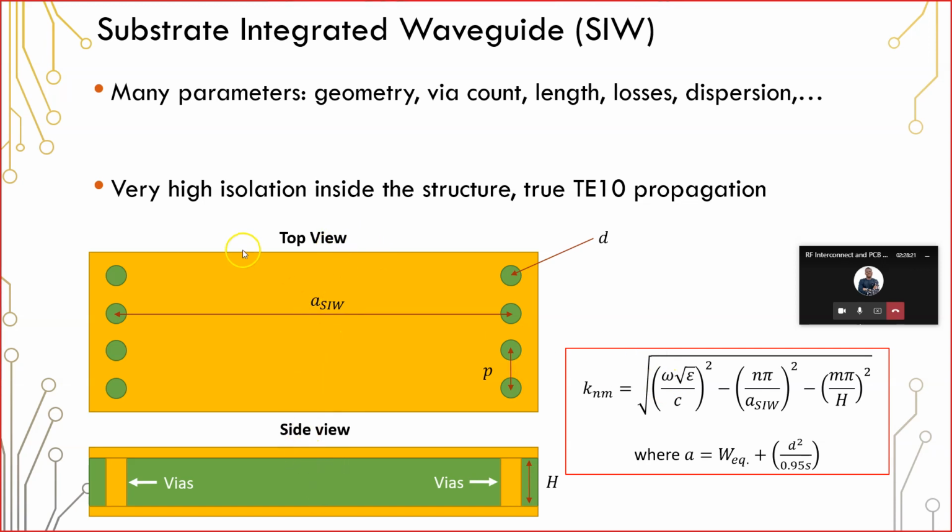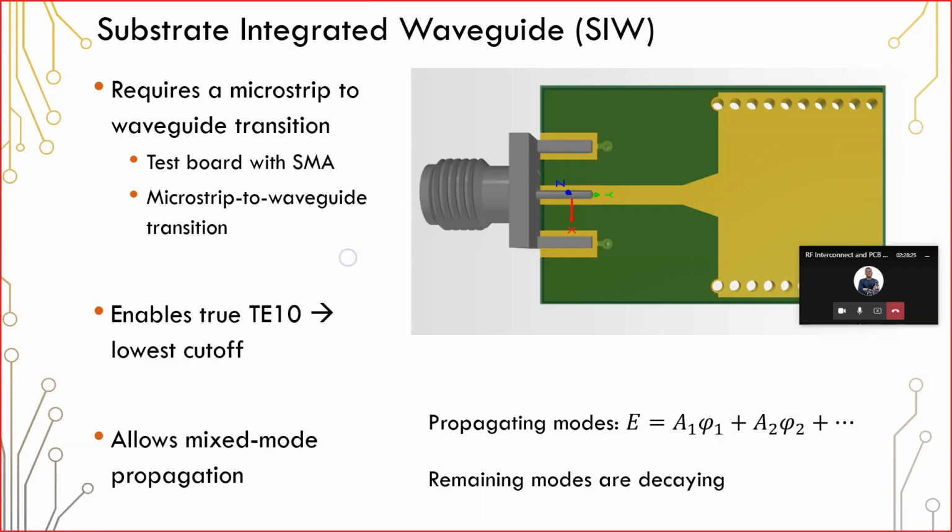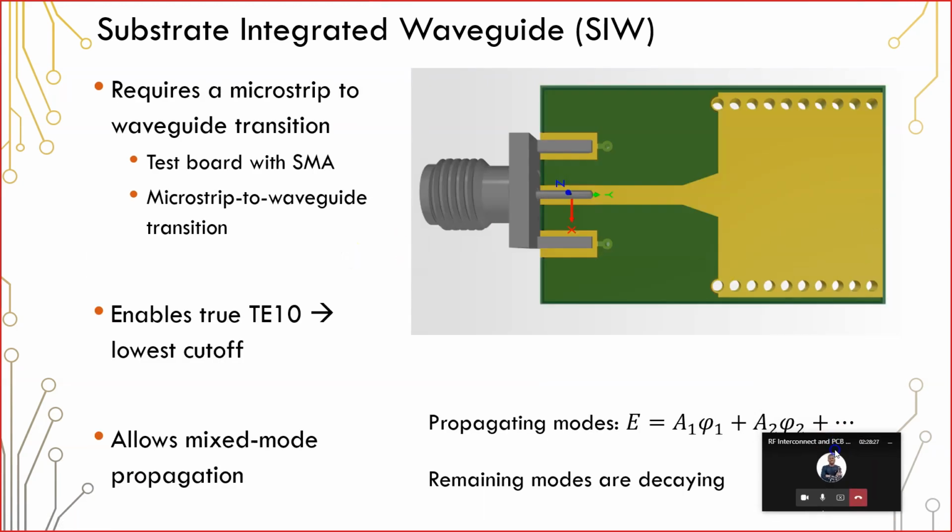down this particular structure. And the reason I would want to know the wavelength is because if I have a slot here in this particular structure, I would like to know the span of the wavelength that is then interacting with that slot. That tells me how big I need to make that slot in order to ensure that I'm transmitting maximum power out of that slot.